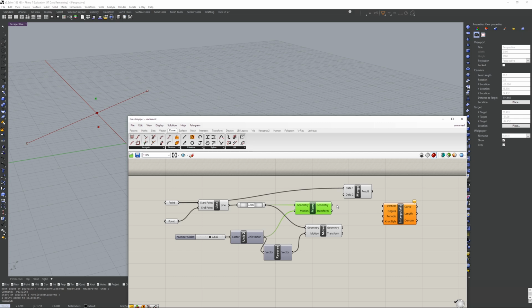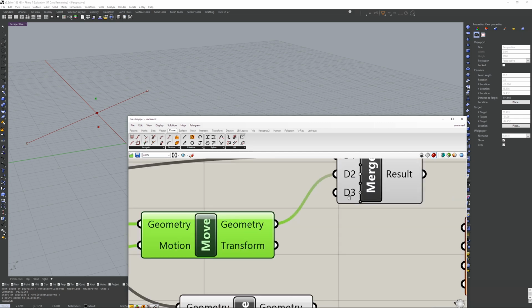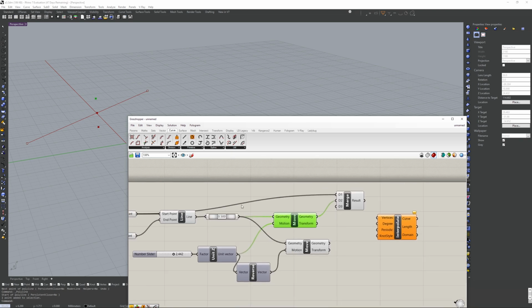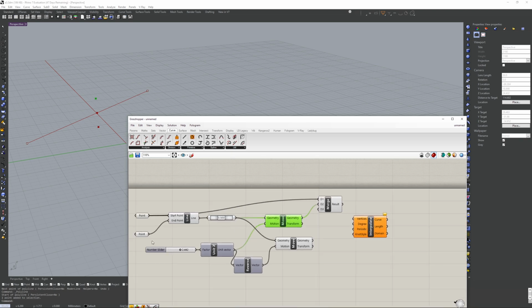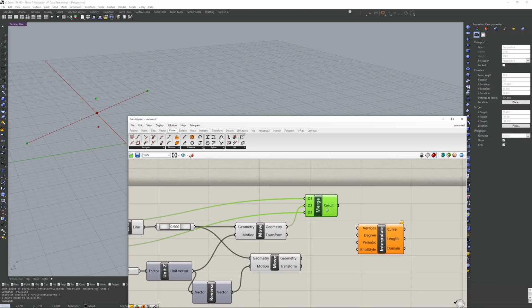So I find that, it's this one, put that in, and it automatically creates a new entry for the next point to go in, and that's going to be this end point here. I can get rid of this extra one just by clicking minus there, and now we have our merged results. If I drag that into the vertices, you'll see it creates an interpolated arc, which is what we want.